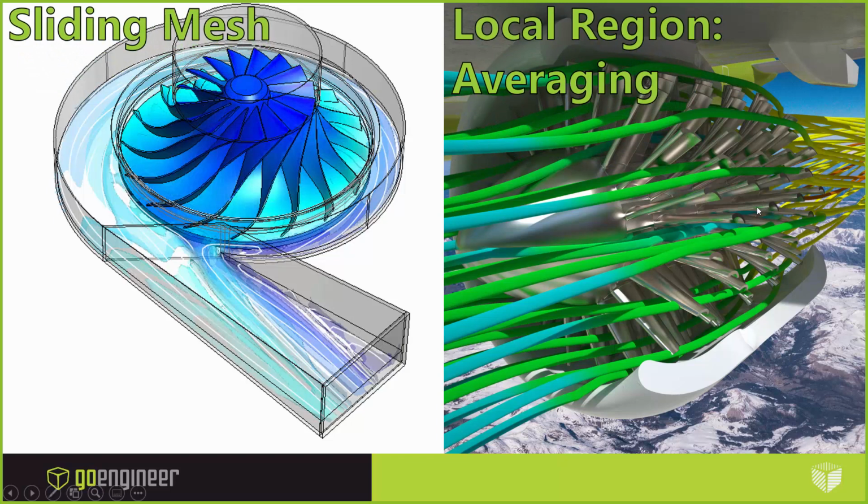Now, again, thinking a little bit further on what makes these examples different, the turbofan is also attached to a plane, which is flying at velocity in a direction. Now, in flow simulation, we don't simulate the parts actually translating or moving in a kinematic way, like a plane flying forward or a piston moving up and down.